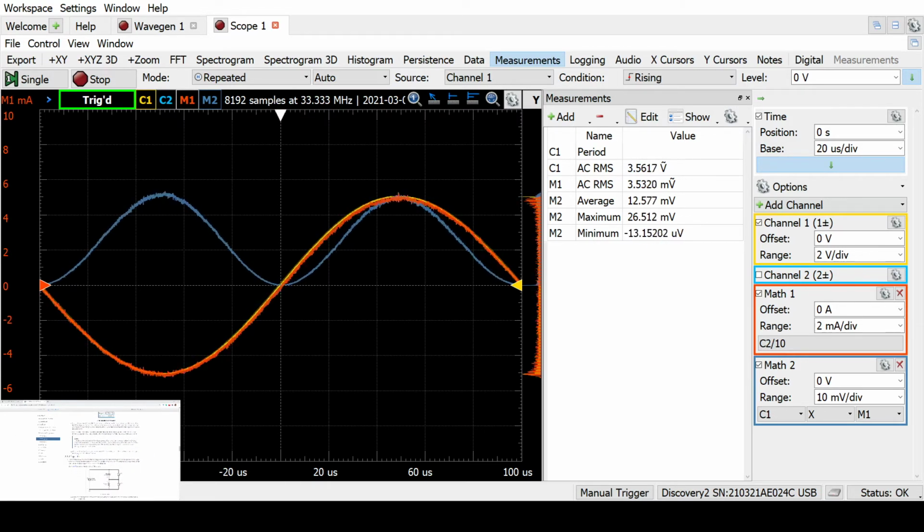Alright, then you will replace this resistor with a capacitor, the 1K, and perform all the experiments. After that, in section 2.2.3, you will replace it with the inductor and then perform all the experiments. Then you will move to the series RLC circuit. So in this one, you will simply connect your capacitor with the inductor and then the resistor.